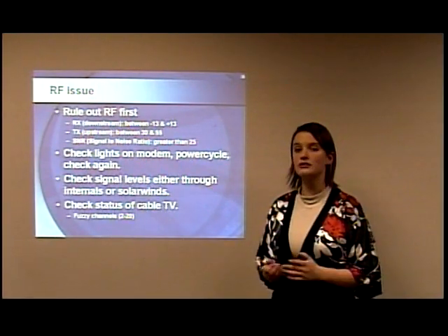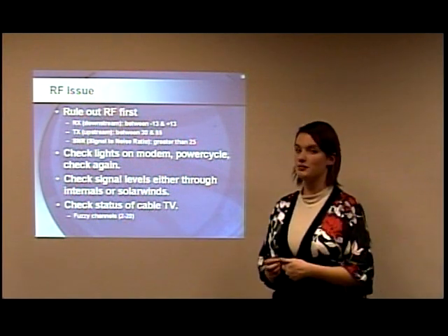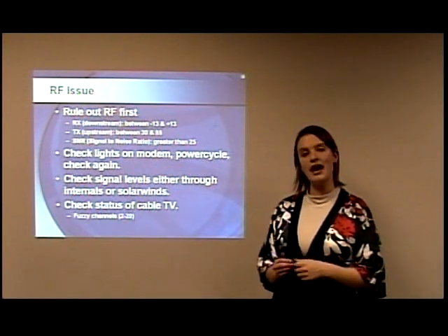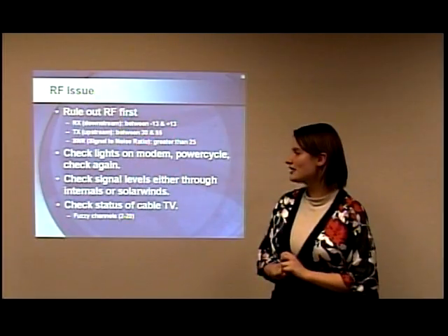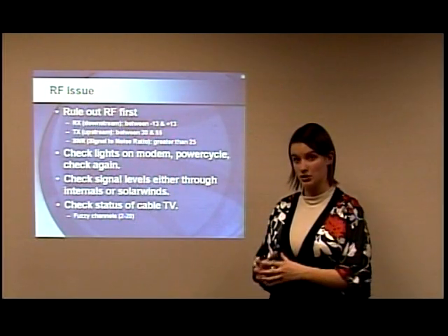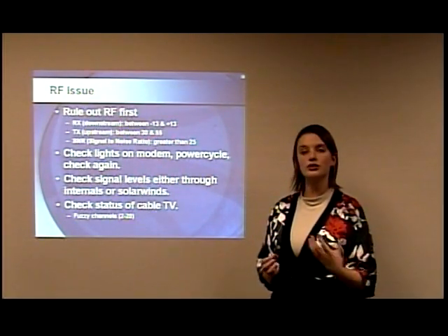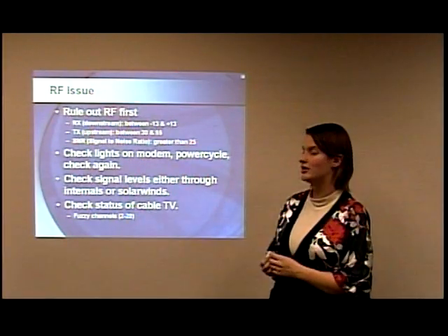Another thing you can do is check the lights on the modem, power cycle the modem, and check the lights again to see if they're still bad or if they go good. Check the signal levels. You can use either the modem internals, which is probably the most accurate, or you can use SolarWinds, which you can check on your end.